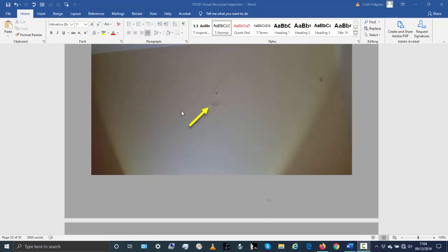The first coat of paint that went on may have been too thick, and it did not adhere very well, and now it's bubbling and peeling off. It may be happening due to minor amounts of condensation on the wall, but as I say, it's reading currently dry, so it's not a major source of dampness. All I would do is clean off the loose paint and paint it again.